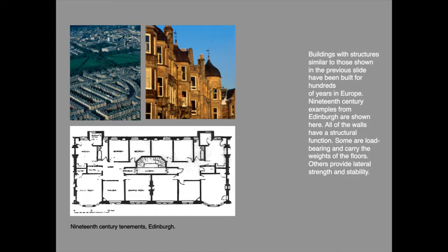The non-load-bearing walls that run in the horizontal direction in the plan also have a structural function because they act as bracing, which prevents the building from falling over like a pack of cards. So all the walls in this building actually have a structural function, and they also have space-dividing or enclosing functions. There is complete integration of structural and space planning.